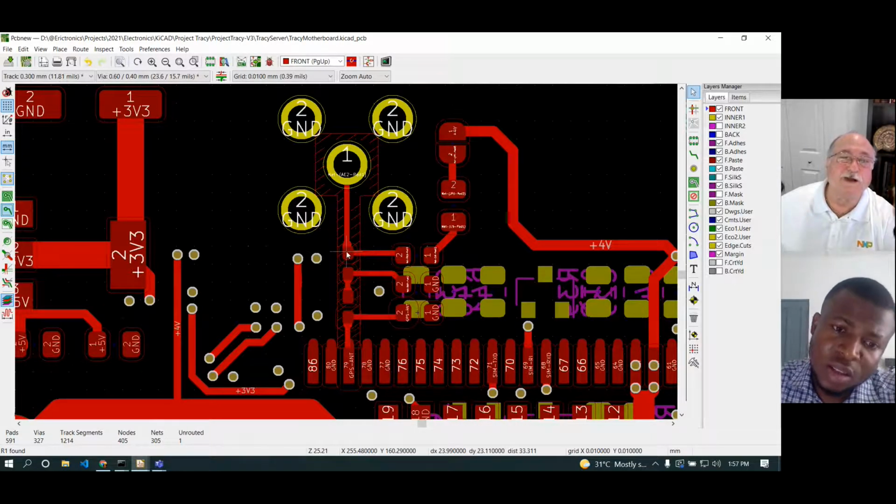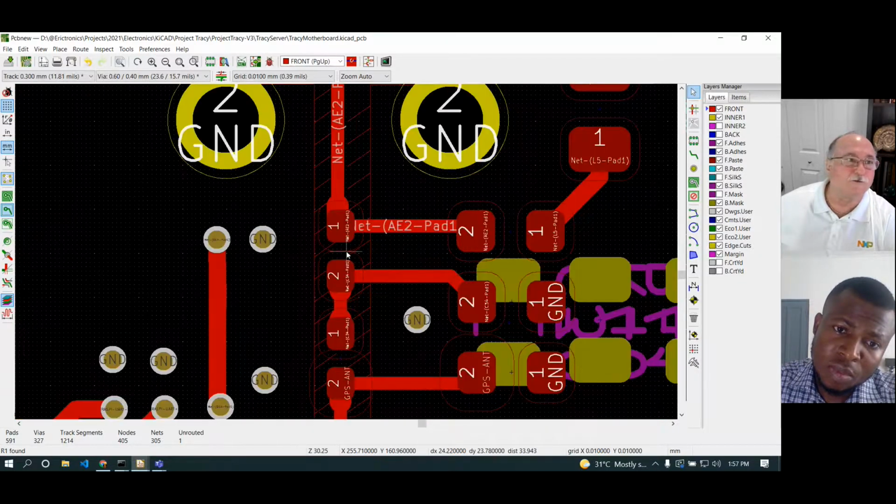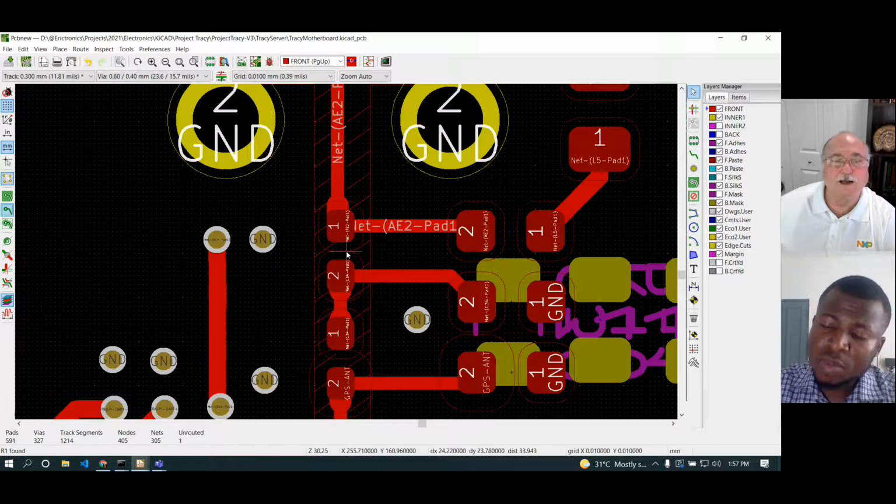That's one of the things, and that goes down where people were talking about, oh, you can't have right angles, you can't have sharp corners. None of those discontinuities matter, because they do change the shape of the wavefront. It sees a larger surface, so there is a change in density of the charge, but they're so small that you can't have that frequency anyway on a printed circuit board.